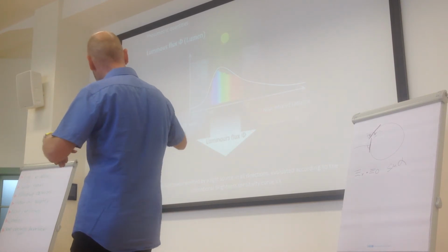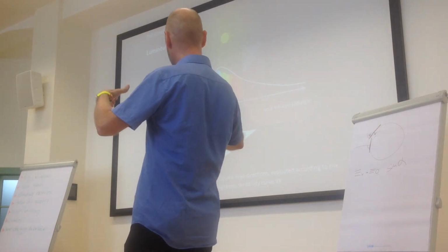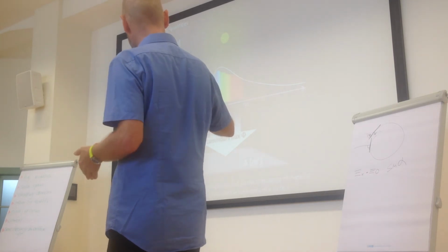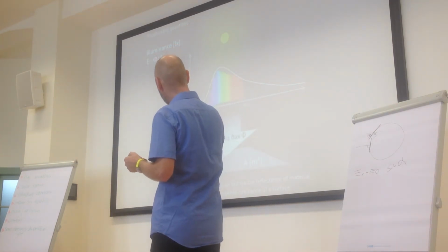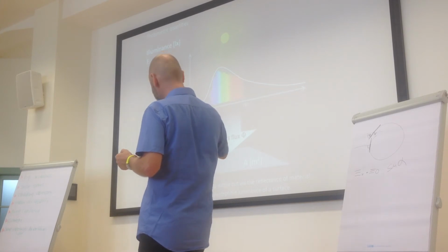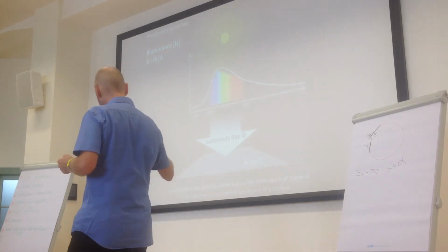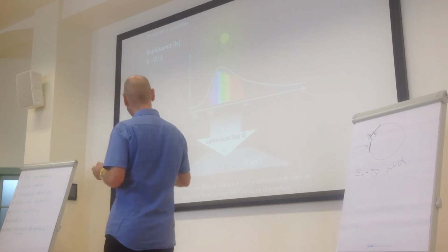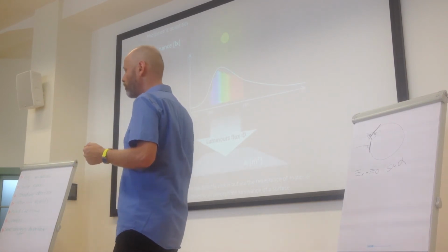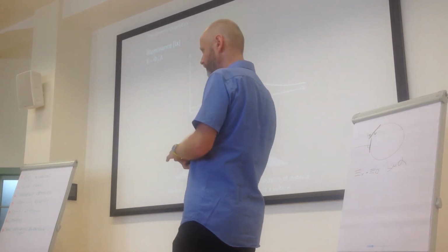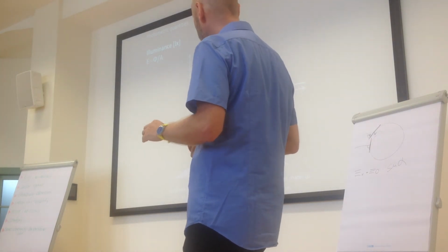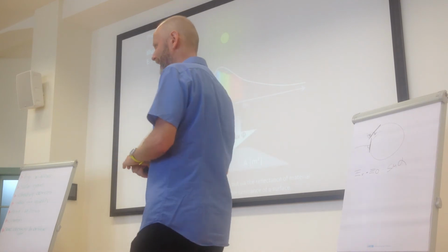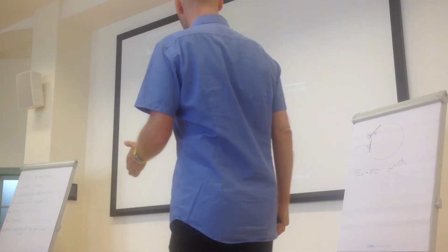And the portion of luminous flux that is coming in on a certain surface, the luminous flux per square meter, is a number that I'm sure all of you will know. It is the illuminance, or lux. And the lux level is basically the most important number when we quantify light indoors or outdoors.